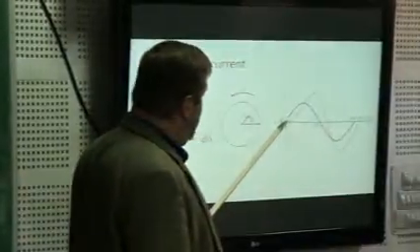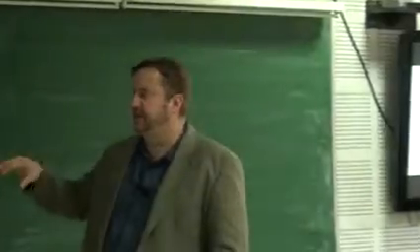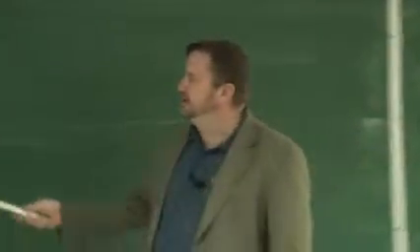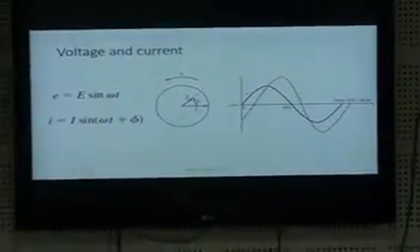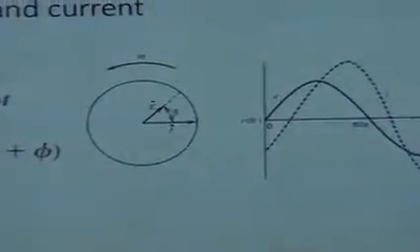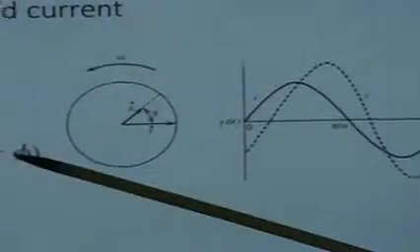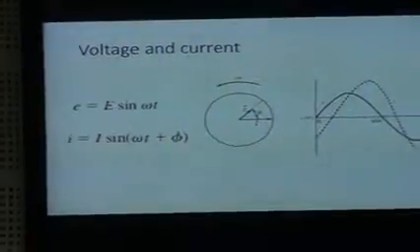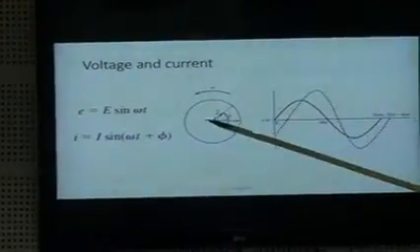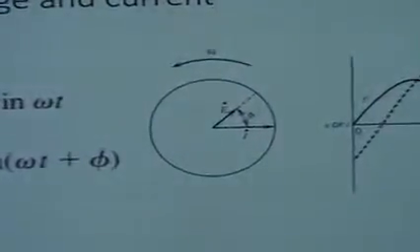If we use the voltage signal as the primary definition of time, then what happens is you get your sine wave, and then your system, for reasons that we'll describe later, responds with some delay, with some phase lag, okay? And that phase lag is all captured in this term phi. You can represent sines and cosines in a complex plane using complex variables, and that's what this phasor diagram shows, the circular entity.